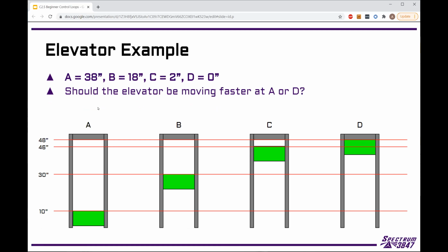Okay, so again, the system is controlling for position. It's trying to move the elevator to a certain position. But all we can really do is command the power of the motor, which controls velocity, right? With the motors that we use, there's no specific way to just tell the motor to move half a rotation or something, right? We're always outputting a voltage, which gets converted to a velocity inside the motor. Some amount of power or electricity is spinning through the motor to move it.